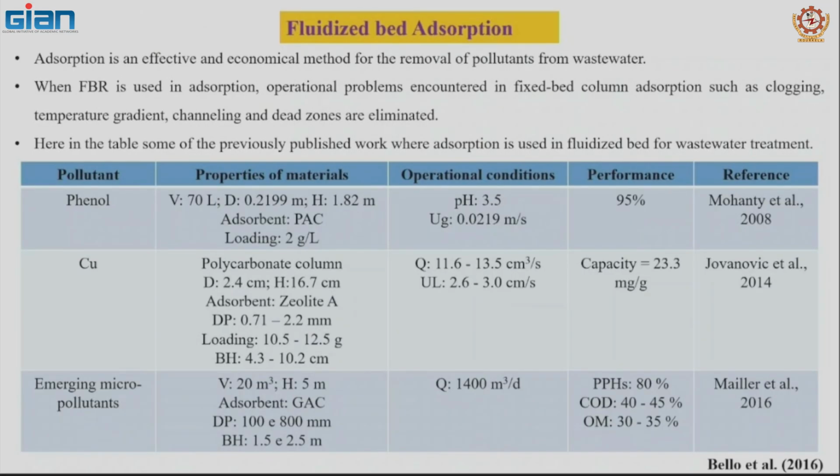When fluidized bed reactor is used in adsorption, the operational problems encountered in the fixed bed column adsorption are clogging of the bed, temperature gradient, local hotspots, and channeling of the fluid, which means all the solid particles do not come into contact with the fluid, so the adsorption is not effective. That is the channeling, and dead zones are also there in fixed column adsorption. These things are eliminated by the use of fluidized bed reactor.